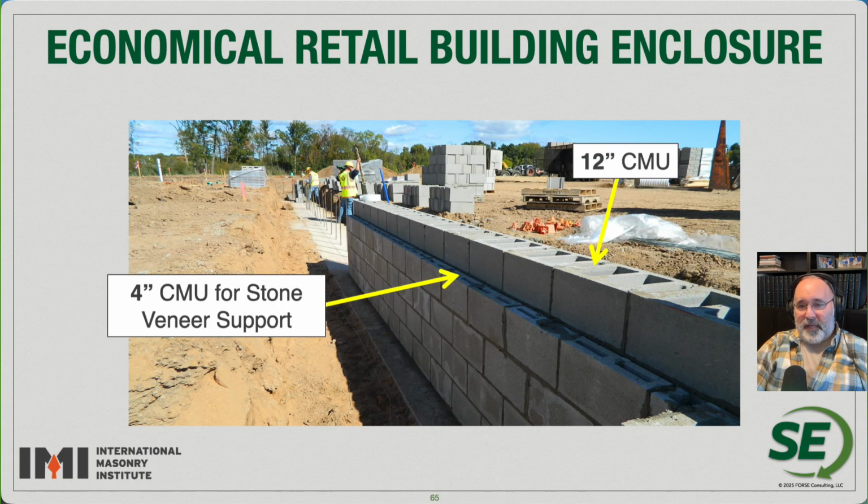Again, looking at different types of foundation systems, looking at a 6-inch masonry. If we only need 12 inches, maybe 12s and 4s can make a very economical foundation wall design instead of getting 16s. And maybe that 12-inch course is going to be able to come up to the slab on grade, and then continue above with a different wall system. So we can combine wythes. We can put a collar joint and some joint reinforcement that would cover these two different wythes below grade.